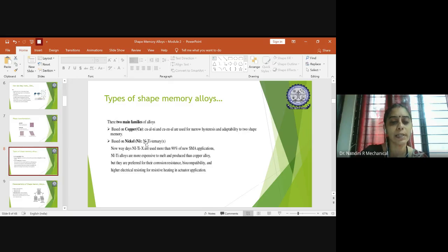combination was totally nickel based. So you have nickel based alloys. So one main familiar composition of alloy is nickel with titanium. So along with nickel and titanium, you have a third element of alloy. Okay, so that used to be used as a type of combination of dopants in order to see that it has the required capabilities to regain its memory of the geometry once it is subjected to cooling. So in that way, the nickel based alloy has a ternary element, and this was represented by the letter X.